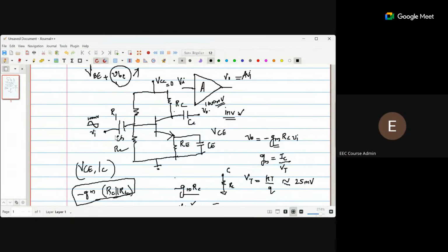So here we had, to the base terminal, one input. If you try to recollect that lecture on the differential amplifier, on this side we are replicating this. That means this part, this transistor, RC, RE. Similarly, on this side RE, and everything, we are ensuring that this RC and this RC are matched. Everything is perfectly matched. Then we are feeding one input to this base terminal, and to the other transistor's base terminal we feed the other input. So V1 and V2.